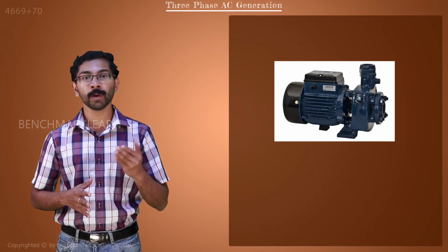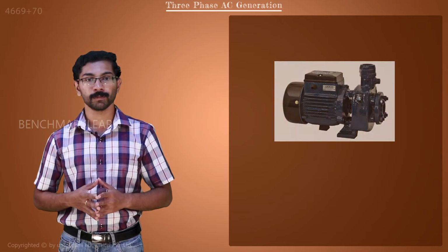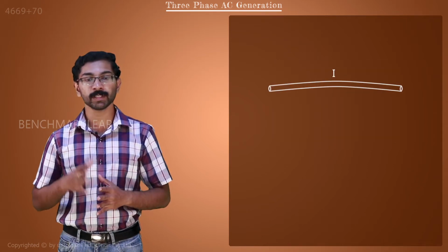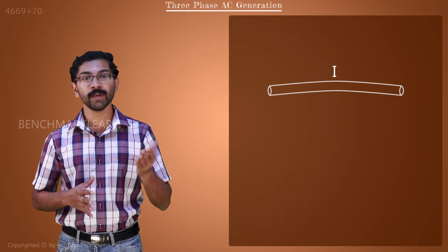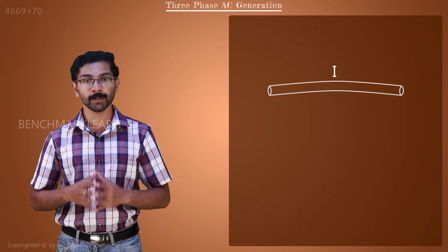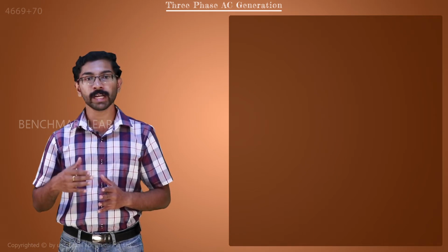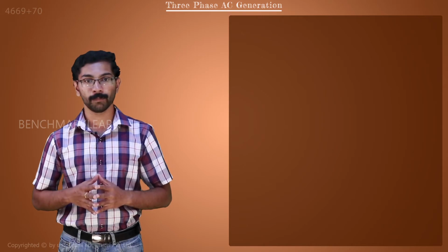To get more power from AC, the device will draw more current from the source. To carry heavy current, the conductors of the transmission line must be very thick. This increases the cost and weight of the conductors. From the viewpoint of the power company like KSEB, this is undesirable. So, there must be a method to transmit large amounts of power with minimum conductor volume.